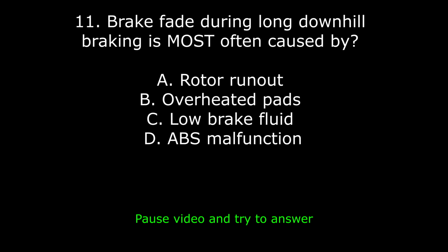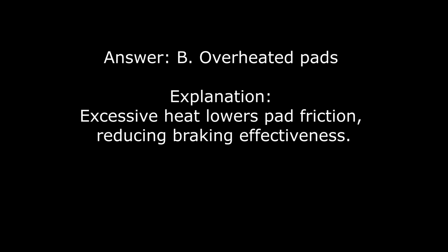11. Brake fade during long downhill braking is most often caused by A. Rotor runout. B. Overheated pads. C. Low brake fluid. D. ABS malfunction. Answer: B. Overheated pads. Explanation: excessive heat lowers pad friction, reducing braking effectiveness.